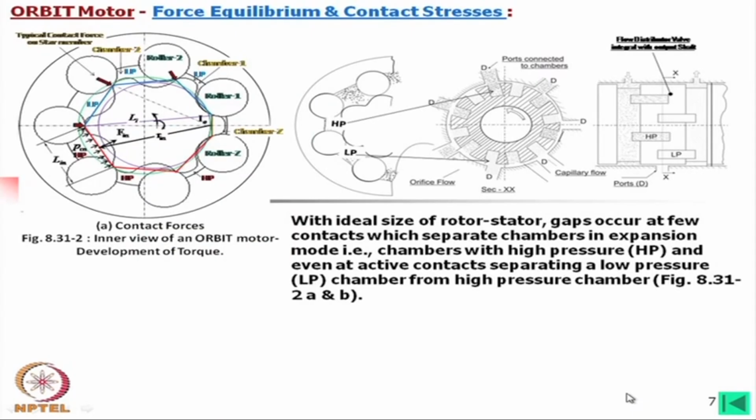Now, with ideal size of rotor stator, gaps occur at few contacts which separate chambers in expansion mode, that is chambers with high pressure, and even at active contact separating low pressure chamber from high pressure chamber. Now, here I would like to mention that we are trying to find out the forces in each and every contact. Then we have considered that apparently